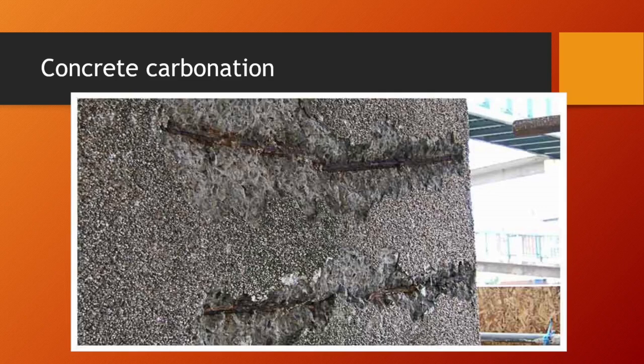And then we've got carbonation, concrete carbonation. So again, it's very similar. It's open to carbon, silica, freeze thaw, everything. This is mostly about acid rain eating away, like a concrete cancer eating away at the concrete itself. There's various things we can do to address that, which is in the first place we can look at half cell potential testing, where we look at the positive and negative electric flow of current through those reinforcement bars.